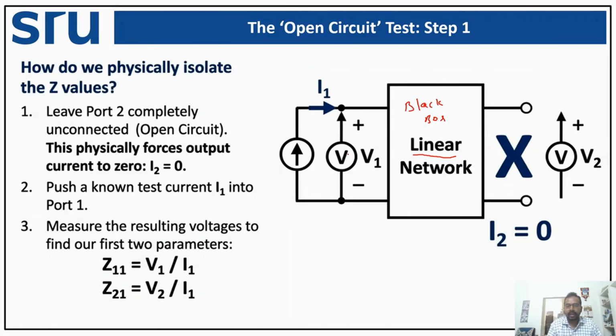So as I said, we have V1, I1 and V2, I2, and we say that the terminal voltages V1 and V2 depend upon the I1 and I2 currents, right? So as I1 and I2 became independent terms and V1 and V2 became dependent terms, we are connecting a current source I1 here, and we have an I2 current.